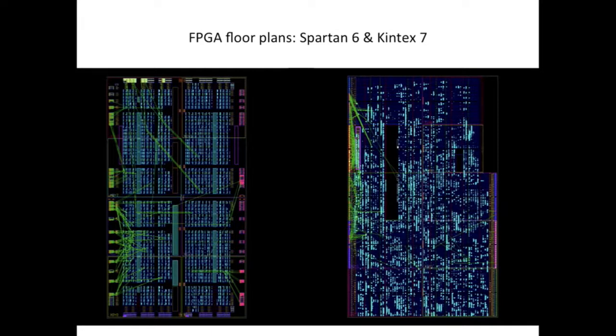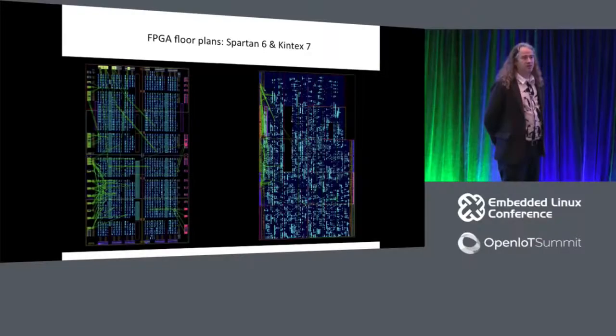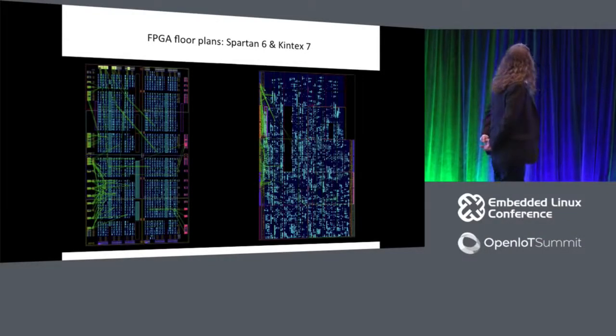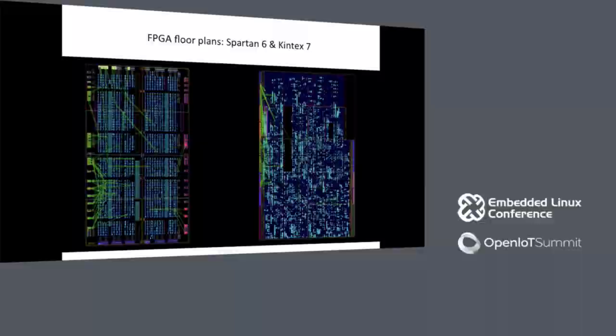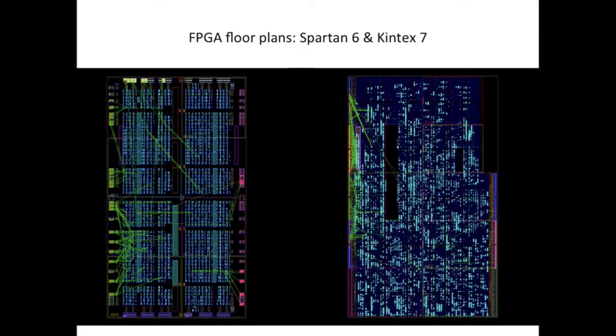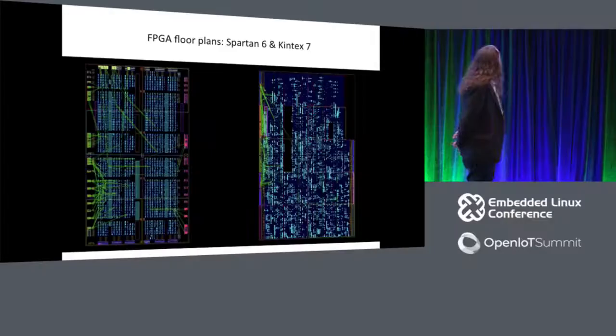They're essentially things like GPS receivers and analog to digital interfaces, DSP hardware accelerators, and stuff like that. And on the left-hand side of this diagram, where all those wires are connected, is the DDR controller. The green wires. There's actually a purple box around the DDR controller up there. Yeah. And the CPU cores, there's a dual-core CPU on that one, and it's clustered there. And on this chip, there are 2 DSPs also, in addition to a bunch of different hardware accelerator cores.